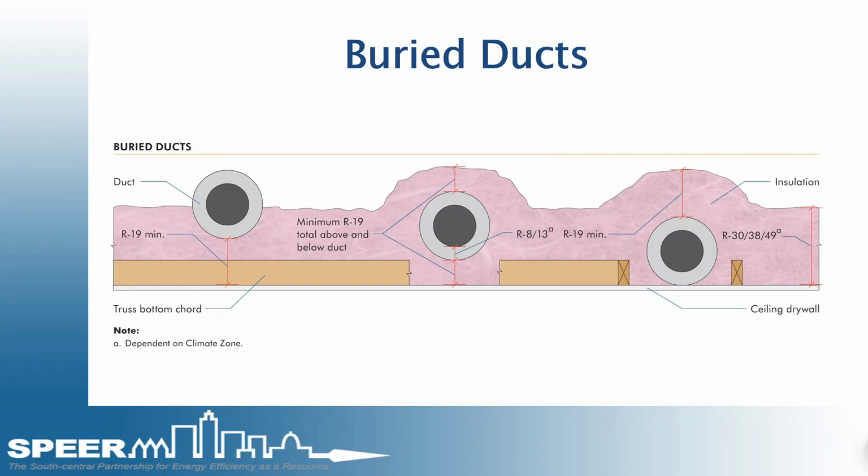So the last one here puts the ducts in direct contact with the conditioned space. Climate zones 1, 2, and 3 are predominantly cooling seasons, so basically burying them completely lessens the chance of heat gain from an attic. If you do that and you do see that, that is now considered ducts in conditioned space. In 2018, they didn't have to be duct tested if they're considered in conditioned space. In 2021 and beyond, you're actually going to have to duct test it regardless of location, even if it's within a conditioned space or encapsulated attic.